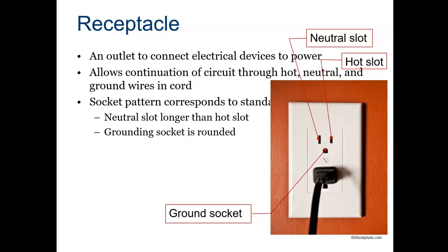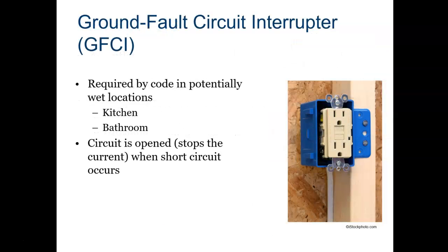Okay, and with that we'll talk about ground fault circuit interrupters, or a GFCI or a GFI as often referred to. They're required by code in potentially wet locations, such as kitchens and bathrooms. The circuit is opened, it stops the circuit, when a short circuit occurs.